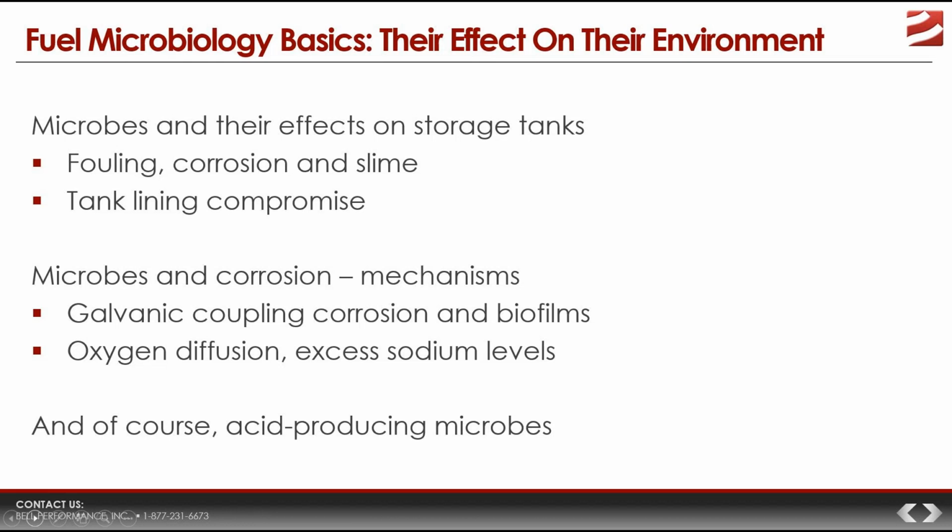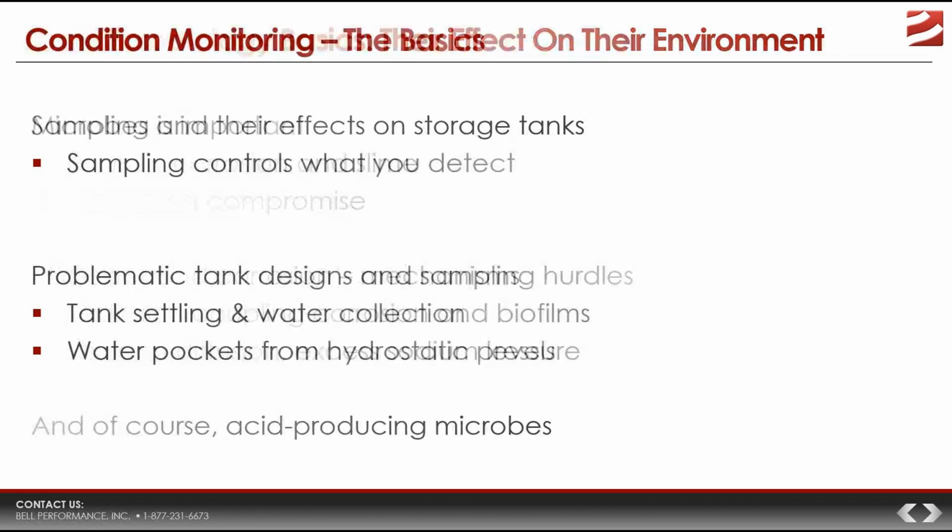And part of the nature of tank corrosion damage and fouling and microbial-induced corrosion is that you're rarely going to find it unless you're actually looking for it. And that means you rarely find it until it has developed to the point where the problems are serious and obvious. And this point has important implications for stored fuel managers. Once the signs of corrosion show up, the damage is already well on its way to having been done. So the goal here is to head off the problem before it develops, before it becomes expensive, which is why we have to consider the issue of condition monitoring here.